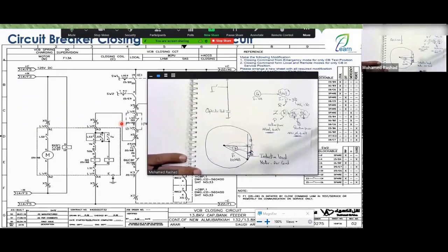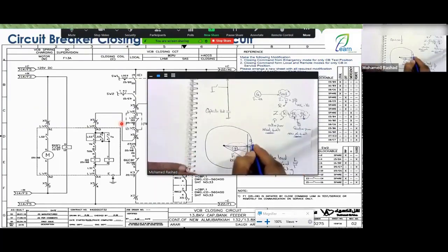All right, like the air conditioners found in factories, exactly like those in factories, and like those in lighting. Lighting is also considered an inductive load. Anything with a coil is considered an inductive load, and it draws Q. The capacitor provides Q, so here we can say this is QL and this is QC.